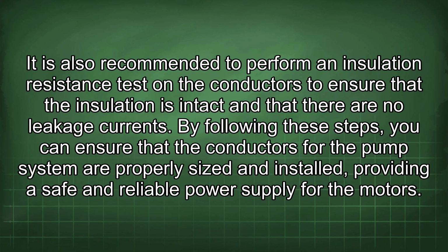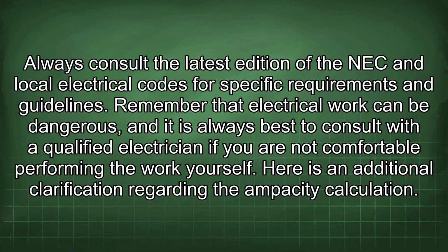It is also recommended to perform an insulation resistance test on the conductors to ensure that the insulation is intact and that there are no leakage currents. By following these steps, you can ensure that the conductors for the pump system are properly sized and installed, providing a safe and reliable power supply for the motors. Always consult the latest edition of the NEC and local electrical codes for specific requirements and guidelines.